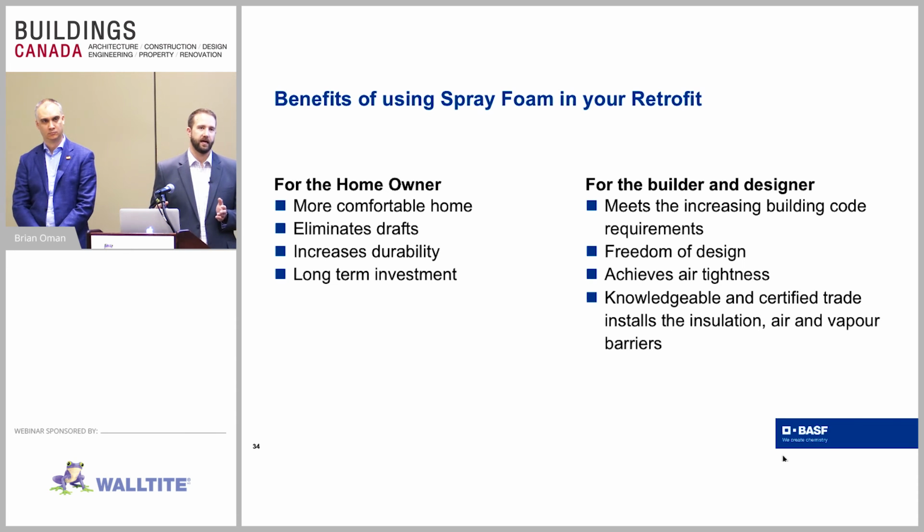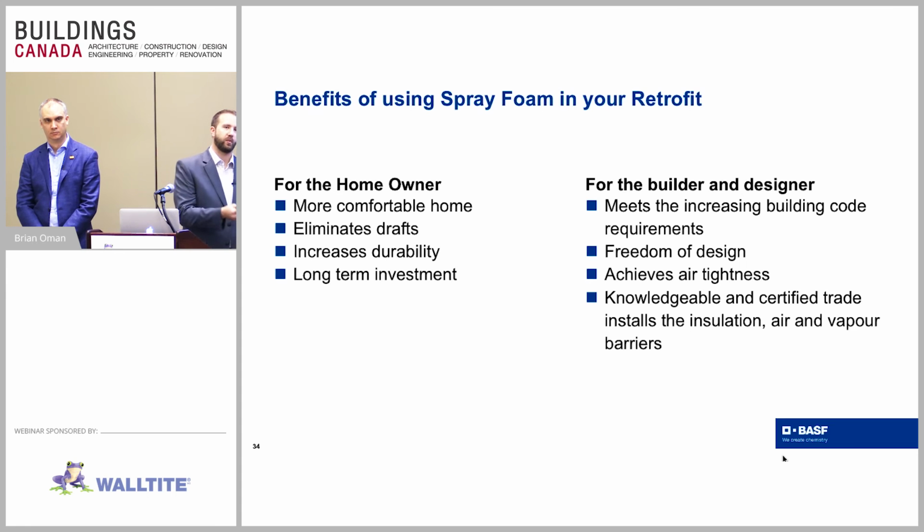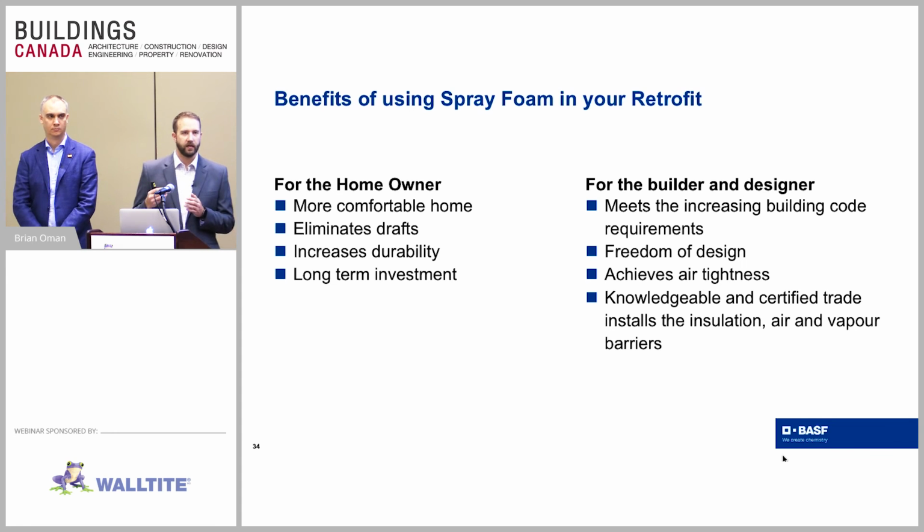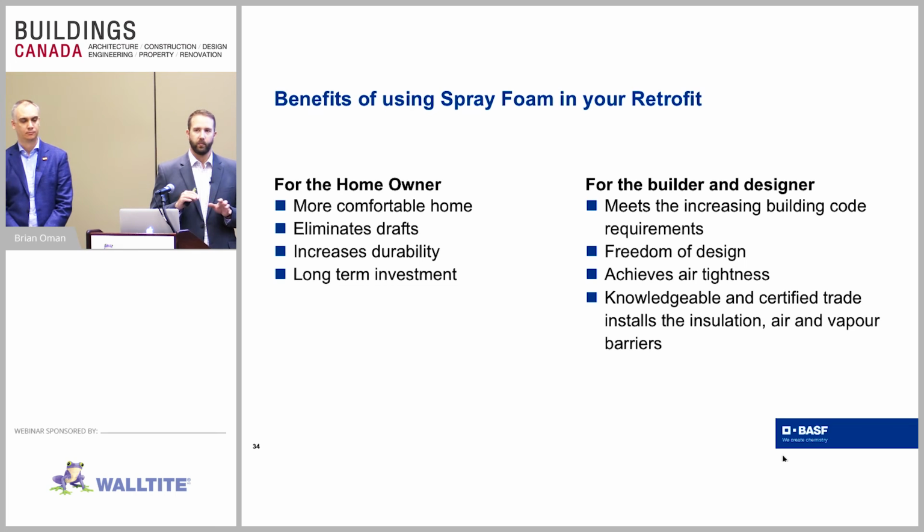We run into a lot of cases where people ask how to remove it. In terms of adhesion, it's going to be there, and there is flexibility, but it comes down to how the product has been applied. If it hasn't been applied properly, that's when you may get a crack or a delamination. It's probably due to improper processing or application. That's why the installer is so important.